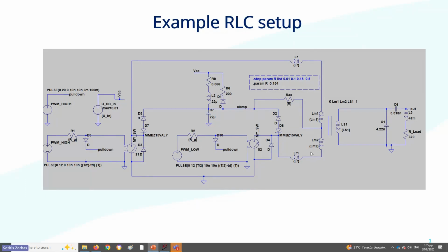So we have a 50%. We're going to see the LT spice in a minute, but this is pretty much 50% turning on this node and 50% turning on this node. And then this is actually a transducer load. This is an RLC of sorts, but this is a Van Dyke model of an ultrasonic transducer. And this is a pulse driving application, essentially.